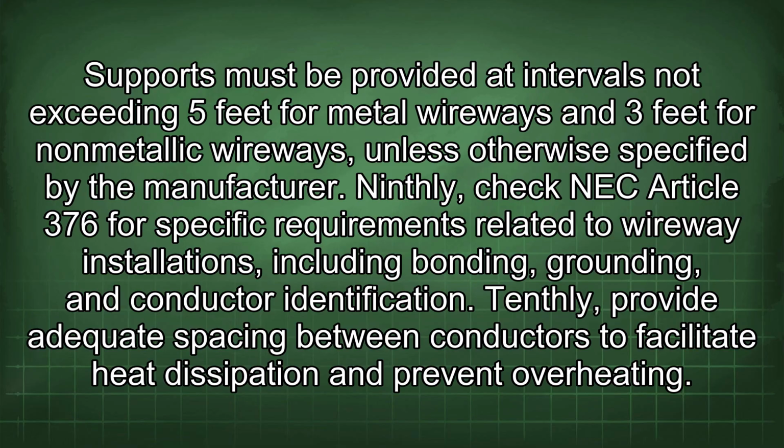Ninthly, check NEC Article 376 for specific requirements related to wireway installations, including bonding, grounding, and conductor identification.